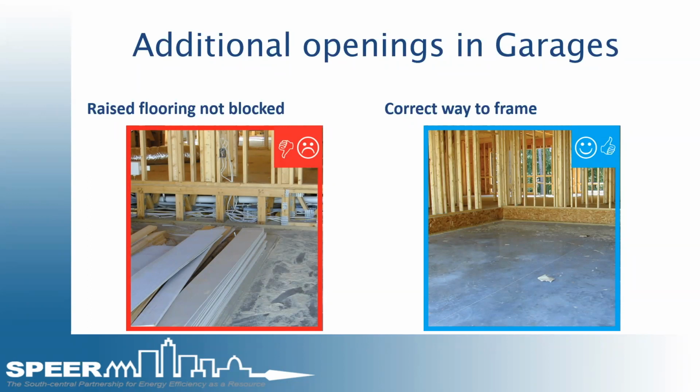The one on the right-hand side is the correct way to frame it. It's got a TJI put there, and it's actually attached to that framing part of it and holding up the wall, or just some OSB that's been cut for that. But the one on the left-hand side is going to have to be blocked and sealed. You can't leave that open from the garage itself.